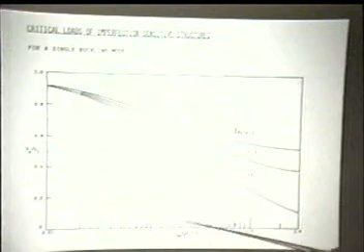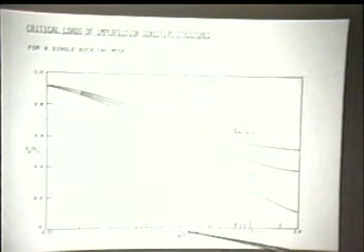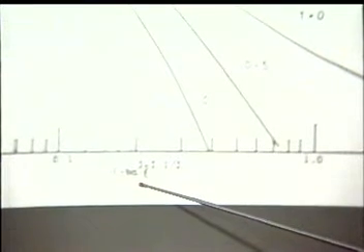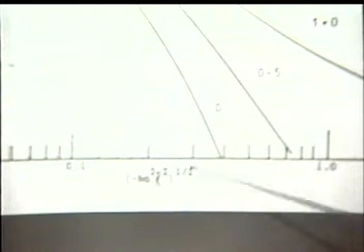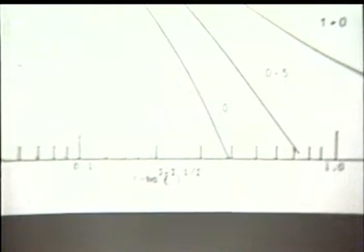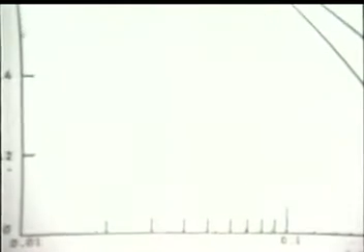Here you have b alpha squared c bar squared in parentheses to the 1/2 power. Notice here is a minus, and it indicates that you only have an imperfection sensitive structure if b is negative. If b is positive, there is no effect of imperfection because here you get an imaginary number. Now if we have the situation alpha is equal to beta, then we are working with this curve here.